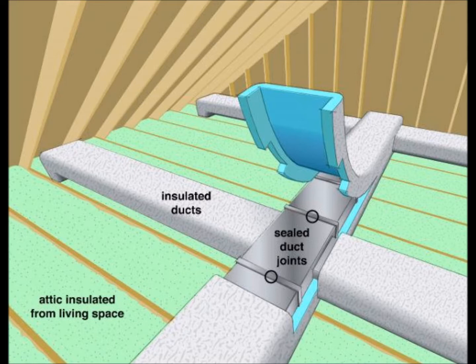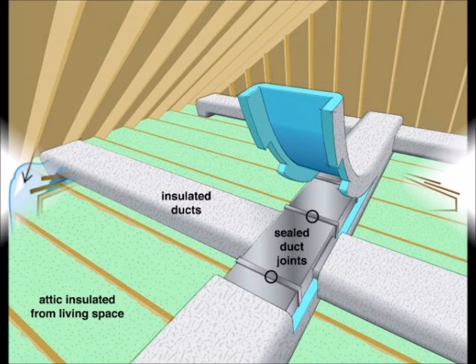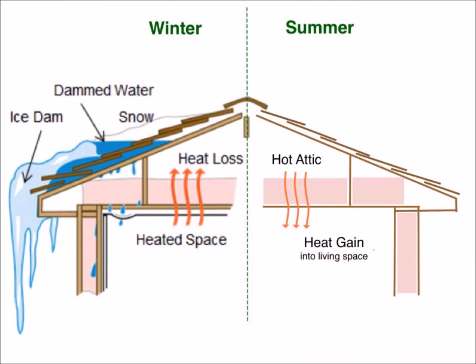Sealing materials include acceptable air barrier materials and durable caulks, weather stripping, tapes, and gaskets, as well as sealants as appropriate. The air barrier material could be a suitable film or a solid material. It's usually most practical to focus on the big leaks that have the big holes, but all obvious air leakage pathways should be sealed.